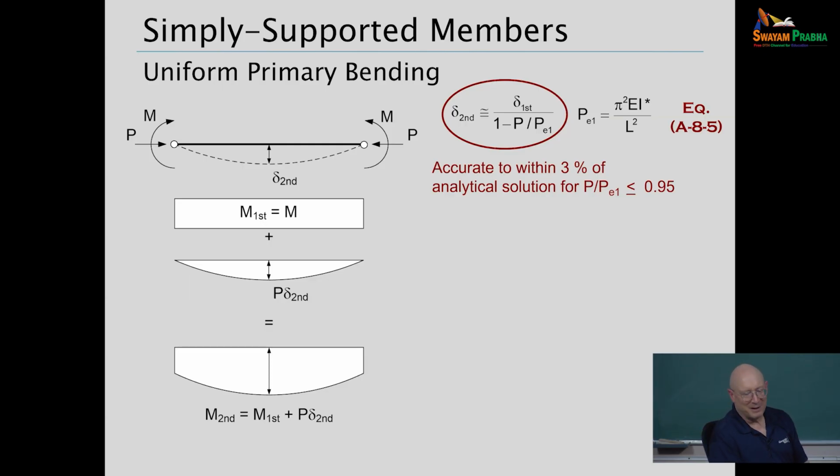But of course we have a deflection of the member in bending, and because of the axial compression, the bending is increased. That's what we call our P small delta effects here. P small delta effects because the ends of the member aren't moving. So we're just looking at the aspect of the axial force P.